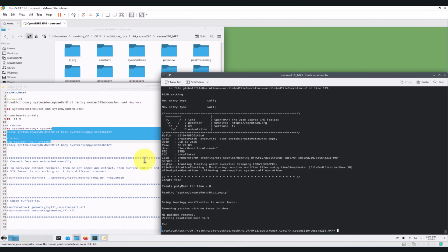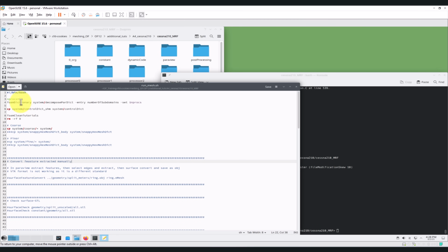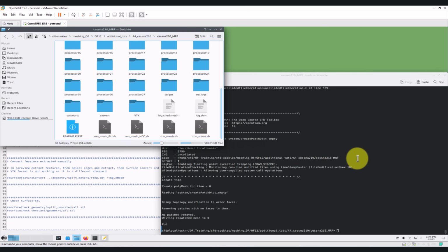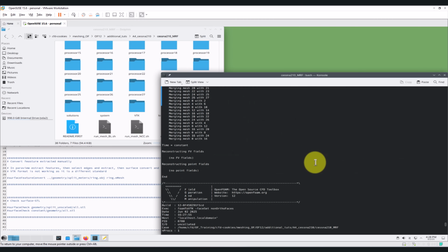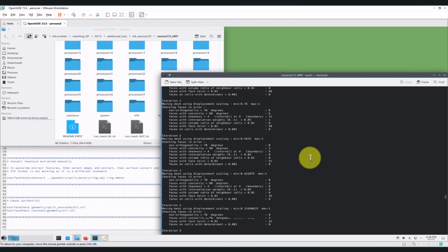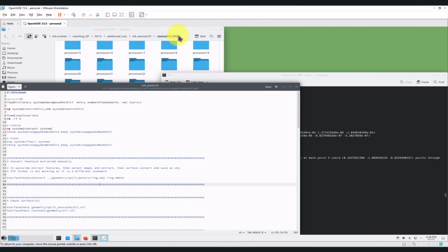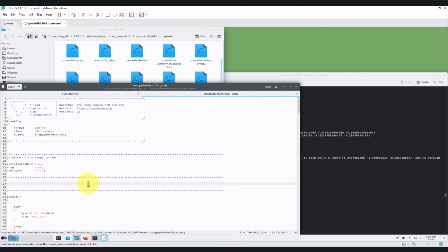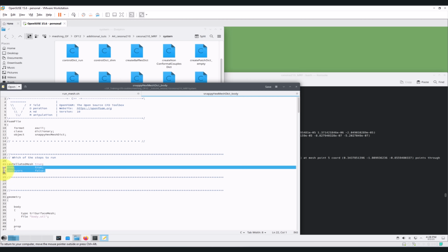Okay, so we're back. We have a mesh. I want to remind you that I'm running with 28 cores, so adjust this one according to your number of cores. Also, we have all the log files. I also want to invite you to read the output on the screen of the machine, and you have everything there. So remember that, and let me go back here and stress, hopefully for the last time, the first step, castellation, is where you do all the cell addition. Snap is where you make the body fitted mesh, and then here you add the boundary layer.